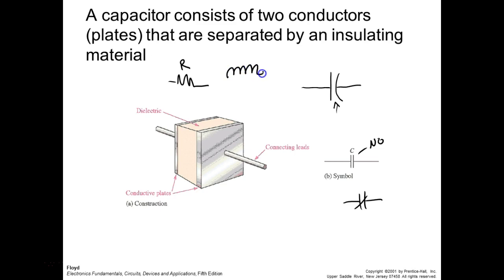This symbol we designate as L. This symbol we designate as C. So you have C1, C2, C3, C4, C5, and stuff like that. These guys are going to have a name depending on what relay. So if I've got a relay over here and it's called John, then the name of this contact is going to be called John because it's being controlled by that relay. So it's real obvious if you know what's going on, especially after you've had controls. So we have these designators.